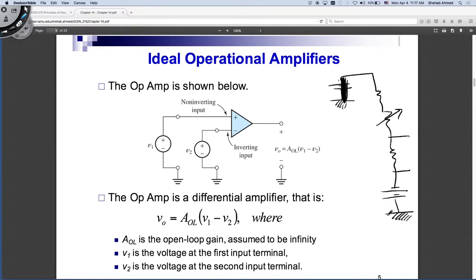It's V input times the resistance R here multiplied with some of the resistance. So my input voltage is negative in this case, right? If I have a positive supply and a negative supply, the op-amp is capable of producing a positive output or a negative output. So that's another interesting benefit of the op-amp versus a simple transistor circuit. In a simple transistor circuit, we looked at simple gain manipulations, etc. But here I can have outputs that are positive, outputs that are negative. I can have outputs that are frequency dependent, and we will see how.